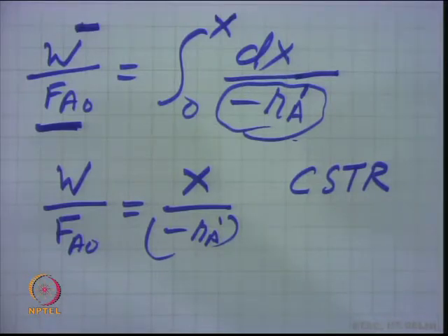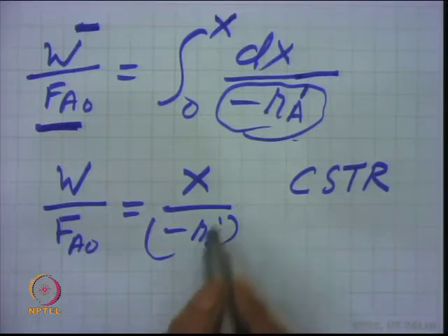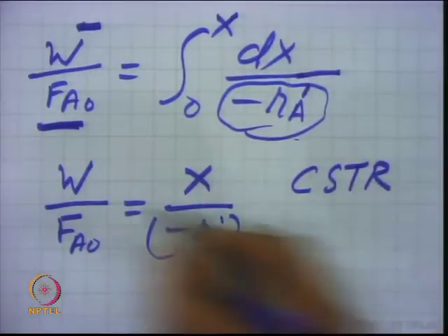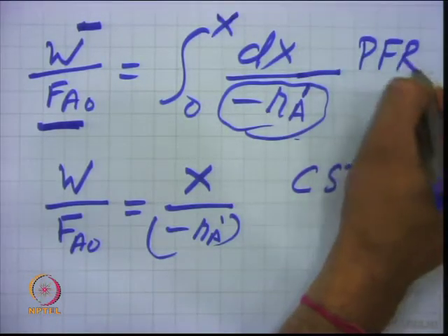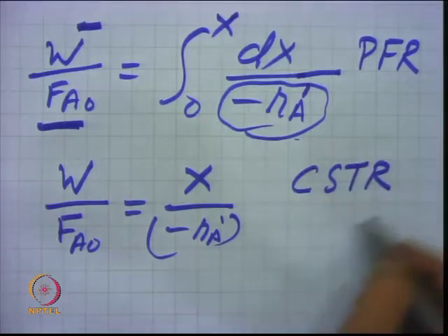But for the actual design of a fluidized bed reactor, you need to look at the 3-phase or 2-phase models to find these rate equations, because there will be a limitation of mass transfer, and accordingly one needs to consider the overall rate of reaction, which includes the resistances for mass transfer in different phases. So, these are the very common design expressions for an ideal plug flow reactor, and this is for the CSTR.